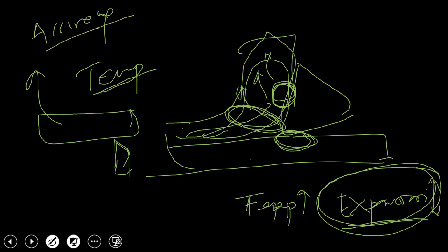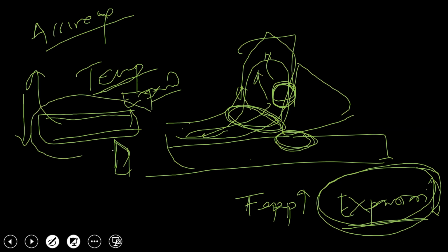Because if you remove material from the workpiece which has expanded because of heat, we know that once it cools, it is going to contract further. So most probably you are not going to get the desirable accuracy.